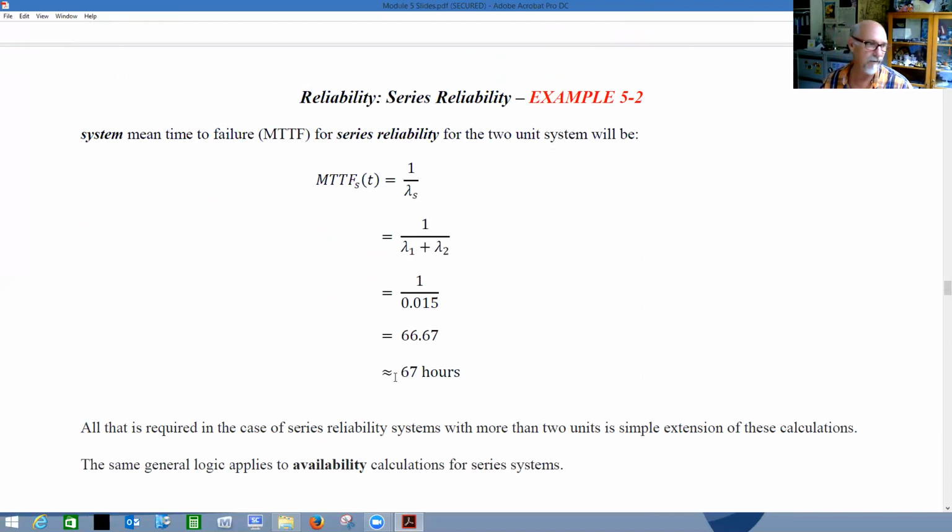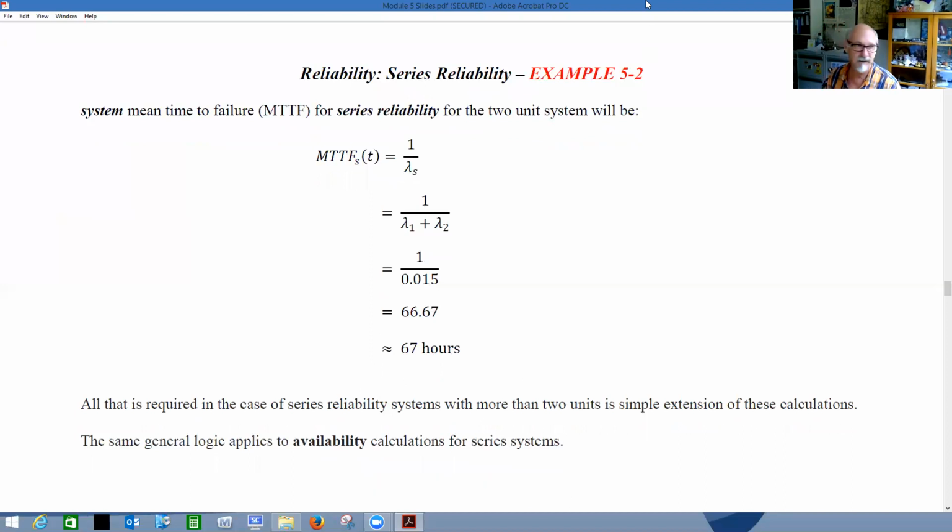So it's not this ad hoc qualitative kind of, oh yeah, you should go and fix that every 100 hours. Well, hang on a minute, if you fix it every 100 hours, sometimes you're going to be okay, and other times we're saying that really the mean time, or the average time, is about 67 hours. So it helps us with the prediction for the failure, but also with the scheduling and planning for our maintenance.